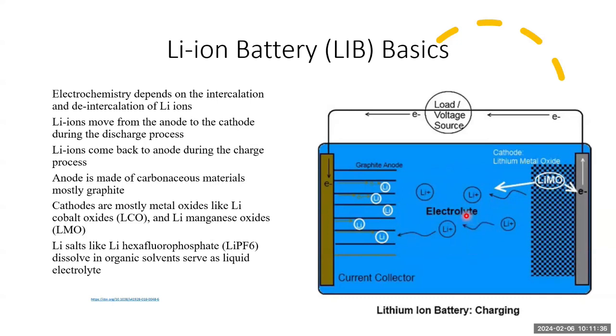That's why this electrolyte is a salt-based liquid, but it is not exactly a good conductor of electricity. It is just a good conductor of lithium ion. That's the specialty of this electrolyte. That's why you can ask, okay, there is a liquid between this. Why is there no electricity or short circuit formed here? Because of that reason. Only lithium passes through it.